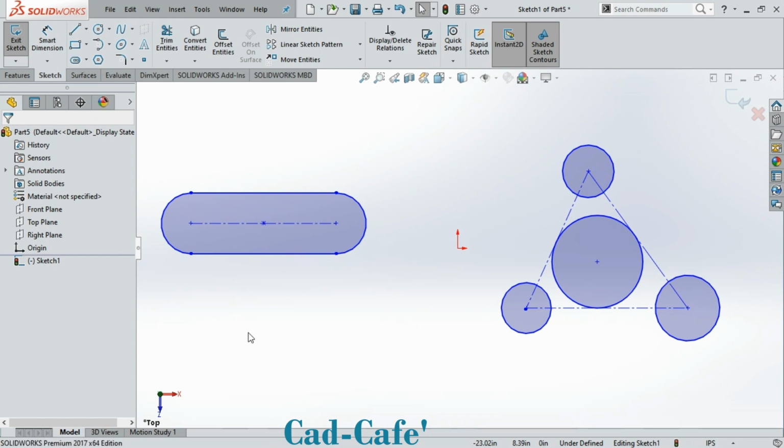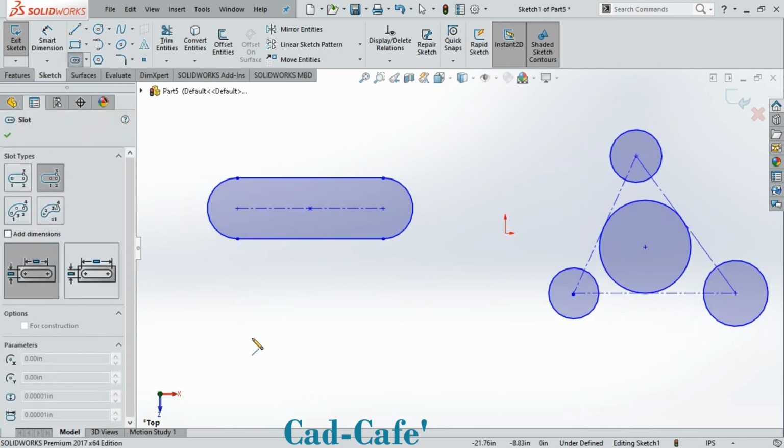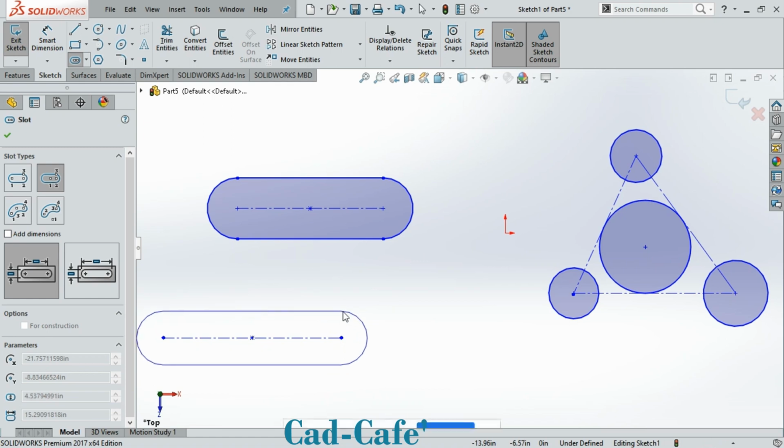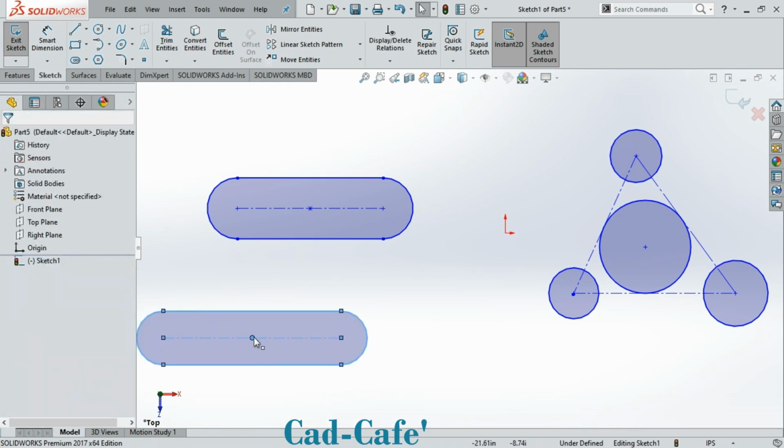Let's assume you've clicked this, and that's the center line or your midpoint. Your axis extends, and then you expand it to whatever dimension you want. So you see, your drawing starts from here instead of here, as opposed to the straight slot. In the straight slot, your drawing started from the first point, but for your second option, the center point straight slot, your drawing started from the midpoint. So that is the difference.